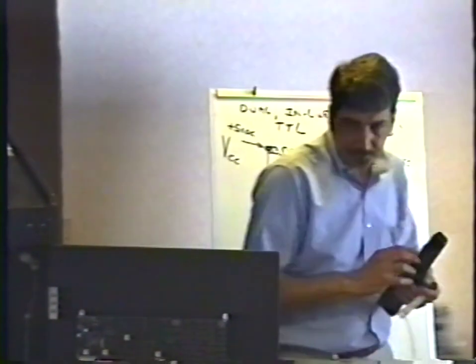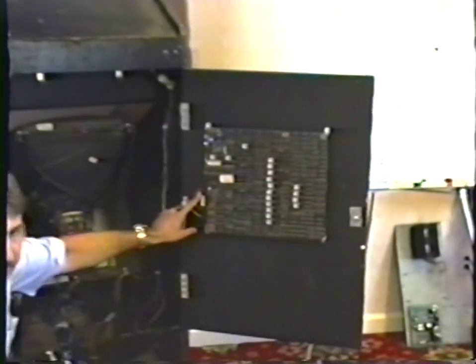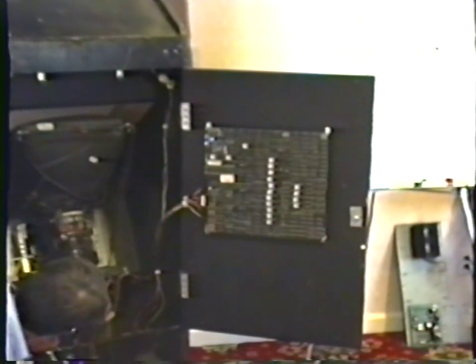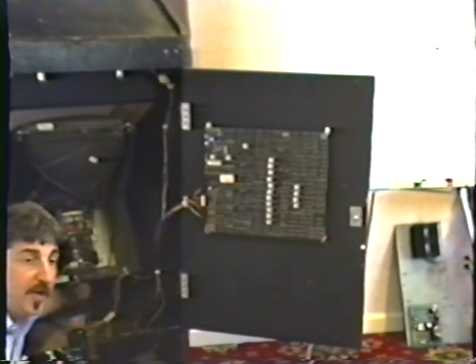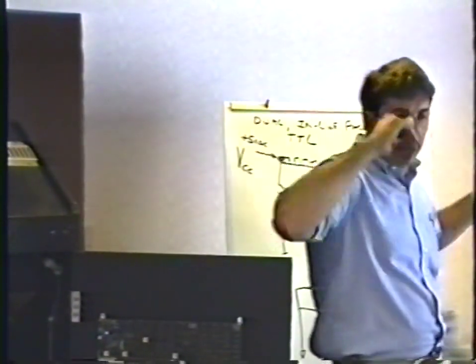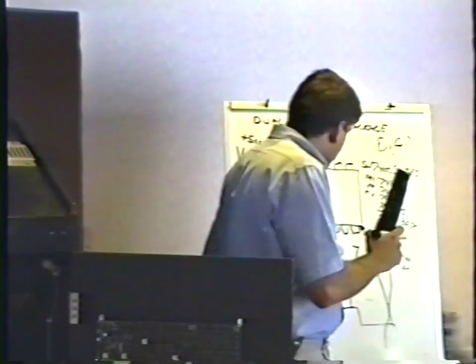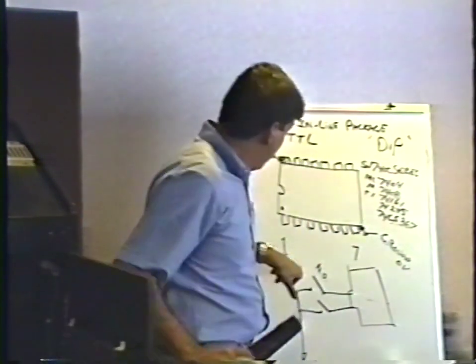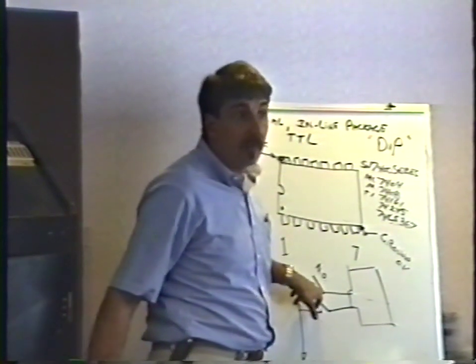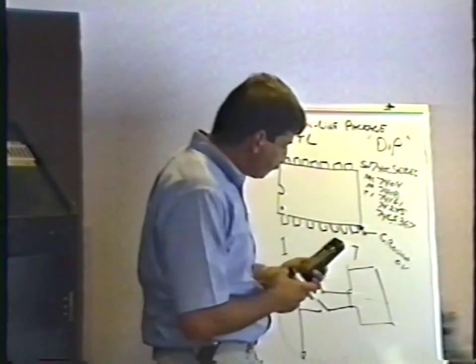If you look at the game, from here the wire goes all the way down here, way up and underneath, and up to the control panel. So the wire is probably a meter long. And it is unterminated. That is, it's sitting there just in the air, basically. It acts like an antenna, is what happens. It acts like a big, long antenna.